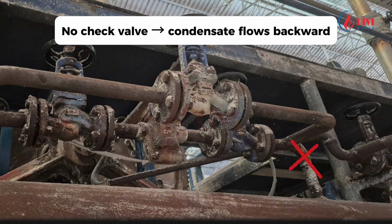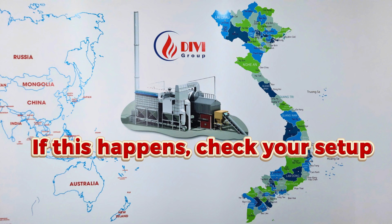Without a check valve, condensate may backflow from one machine to another. This disrupts condensate discharge. One machine might have sufficient heat while another lacks it. If you're experiencing this issue, check your setup.